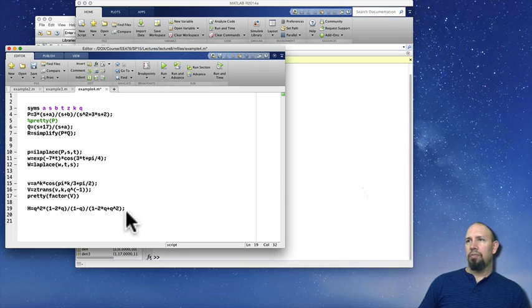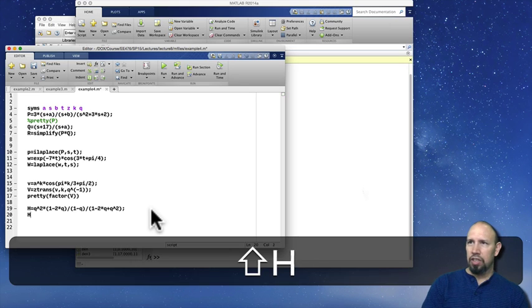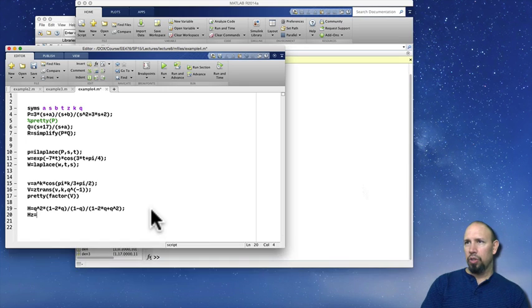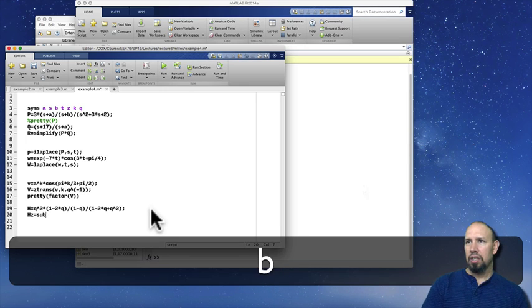So suppose we have some function in q and we want to take the inverse q transform. Well, the first thing, this does z transform, it doesn't do q transform. So if we want to now use the z transform, I first have to convert from q transform into z transform. And so the way to do that is I'm going to do hz is equal to subs, which means substitute, in h for z q to the power minus 1.